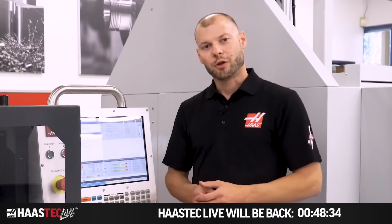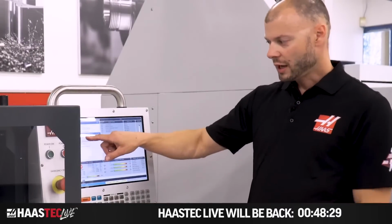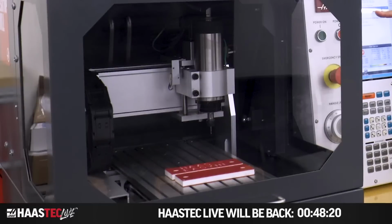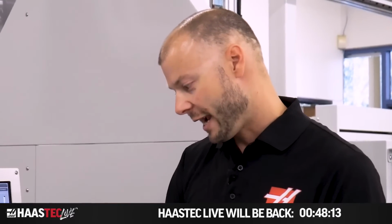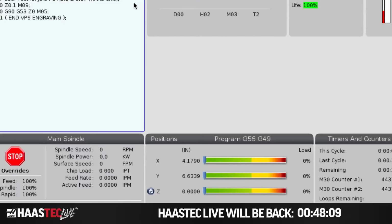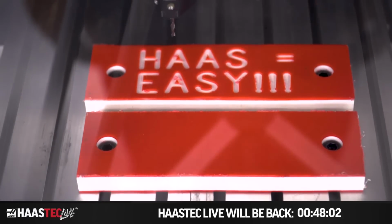Now since the desktop mill doesn't have a tool changer, the first thing it's going to do is move to the back corner to a safe position and ask me if the right tool is loaded in the spindle. This way you can make a program with multiple tools even without a tool changer. But since we already have the tool in the spindle, per the message on the screen, I'm going to push the letter K to continue. And now I'm going to change the rapid override down a little slower. Now that we're moving in the right direction, it looks like. Speed it up a little bit.